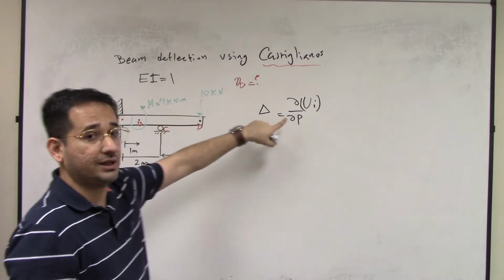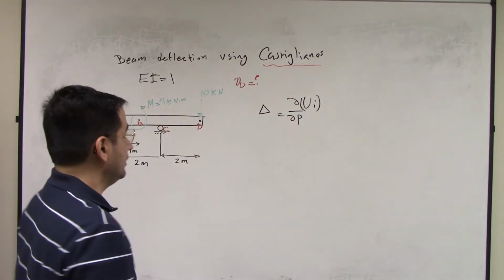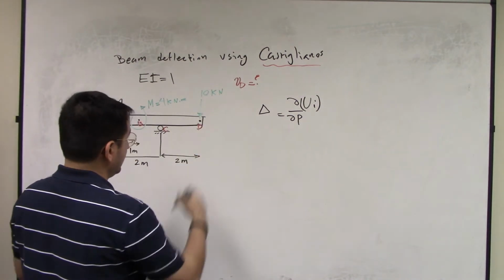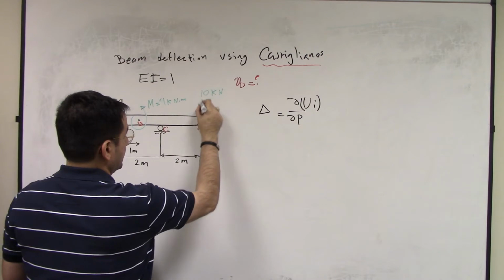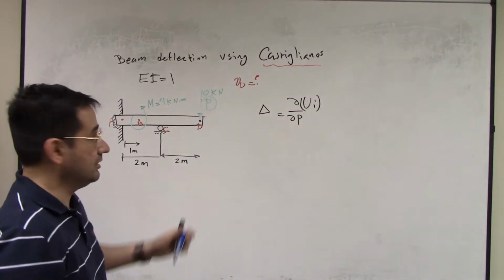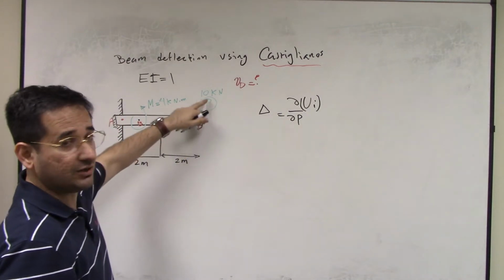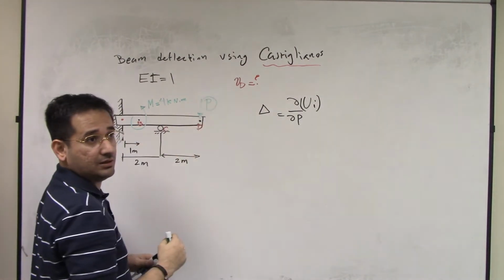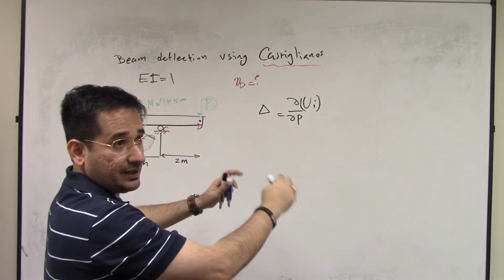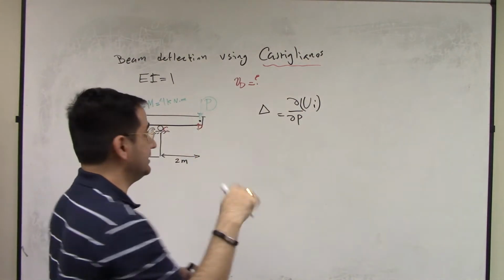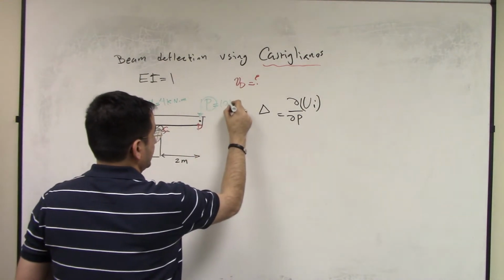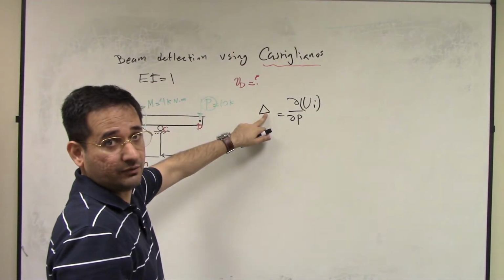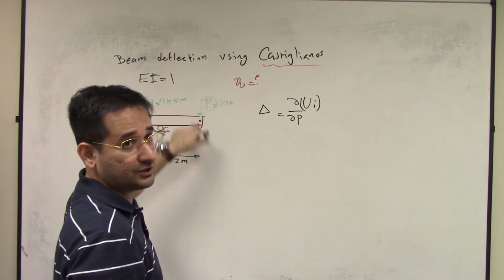So in order to get this trick working, instead of 10K, let's say this is P, right? So assume that the force applied here is not fixed to 10K. It's P. And then once we do all this, after we do the derivative and everything, evaluate it at P equal to 10K. That gives you the numerical value for the deflection at this point.